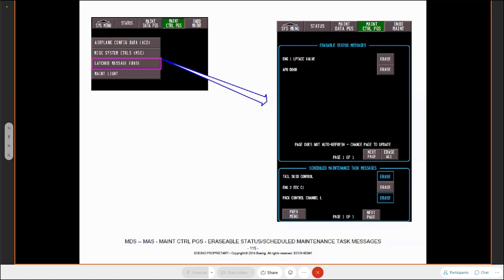As soon as you switch the fuel pumps off, you've no differential pressure, so there's no real fault, because it's the same pressure across the filter. But that message could potentially be latched to tell you that the filter is actually blocked. It's just that you can't see it at the moment. You could replace the filter, do the ground tests and everything else, and then you may have to come in here to erase that latch message.